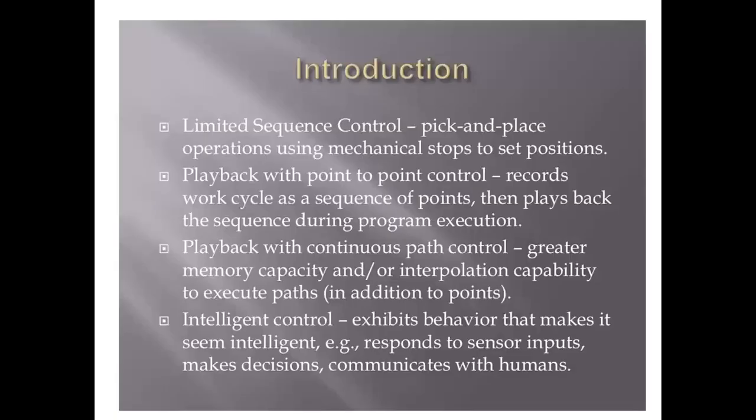So robot control, that is, we have limited sequence controls. We can place operations using mechanical stop executions. When you're going for playback with point-to-point control, we'll have a recorded work cycle as a sequence of points. Then we'll be having the playback sequence during the program execution. So continuous path control, we'll have a greater memory capacity or interpolation capability to execute the path.